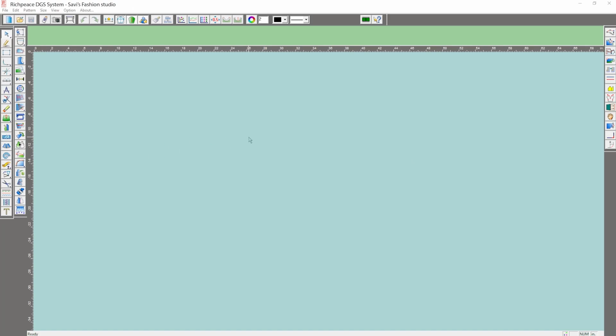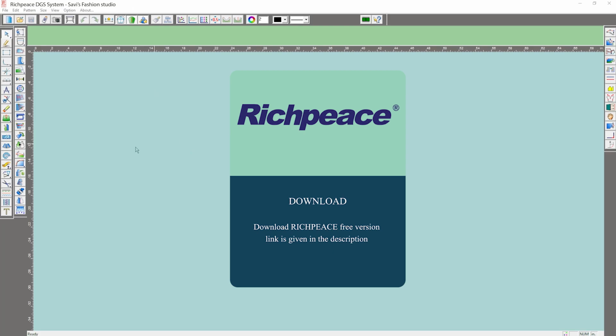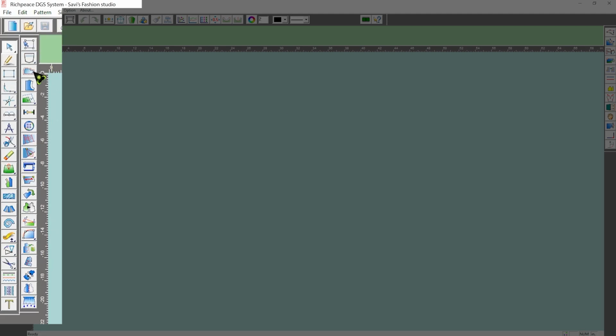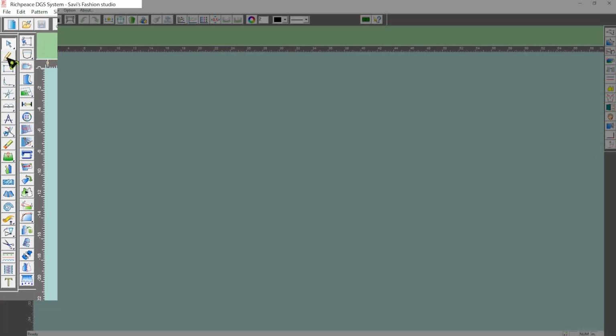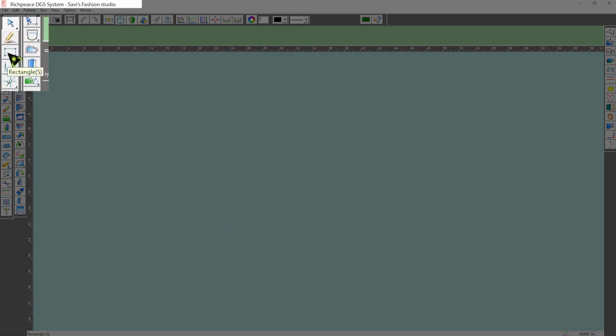In this video, let's see how to make a woman's t-shirt, and to draft the pattern, I'll be using this Richpeace CAD software, which is quite easy to use. Now you see a lot of tools here, but in this video, we'll be using only some of the tools and creating the pattern. First of all, we need to draw a rectangle, for which you can use this rectangle tool. However, we can also use this intelligent pen and draw a rectangle. This can also be used to draw a curve or a straight line. So I'll be using this tool.